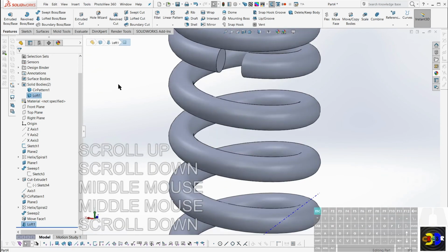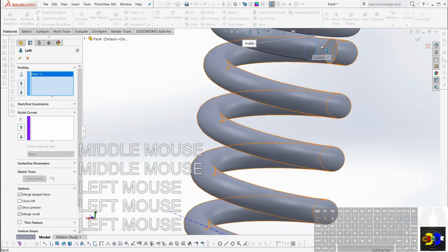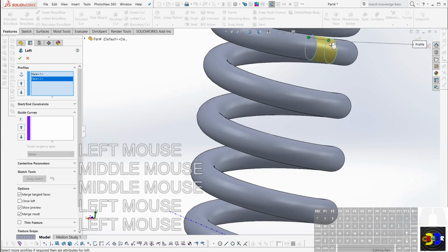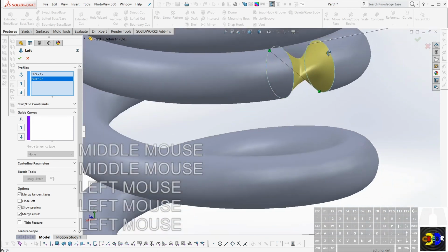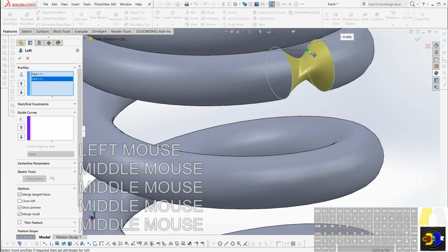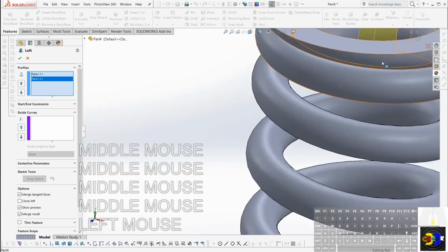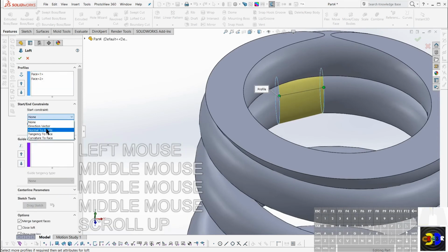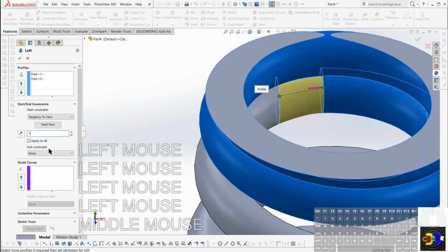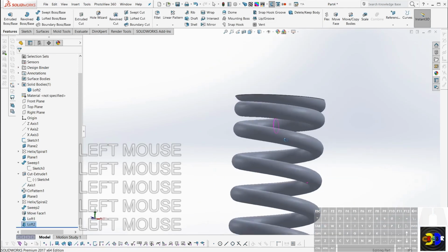And let's do that again up here. Loft from this to this. Now if I do something like this, it gets ugly. So be careful to align these green dots as close to straight along the path as you can, and tell them tangent, and tell this one tangent, and those should be pretty good.